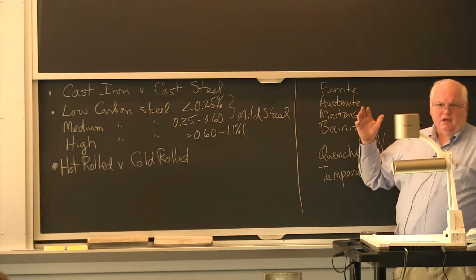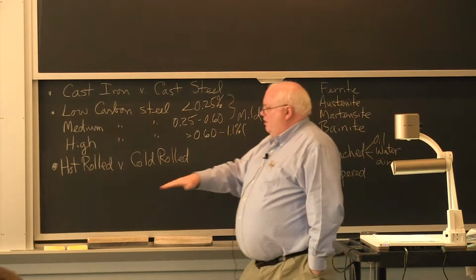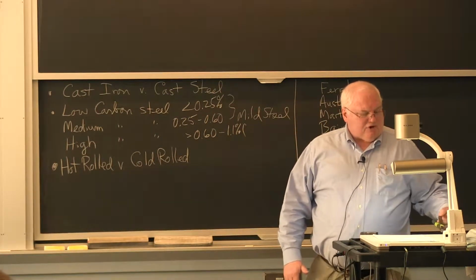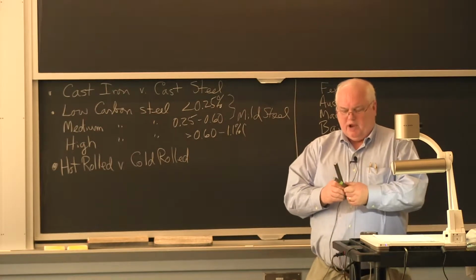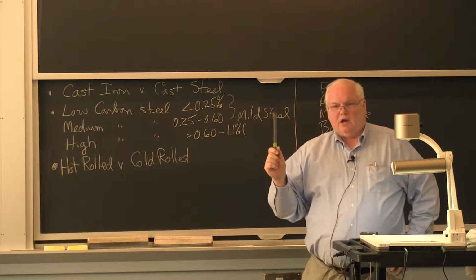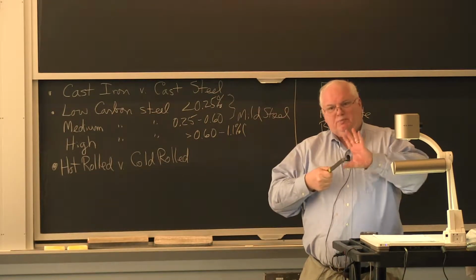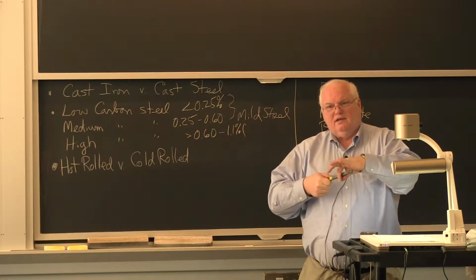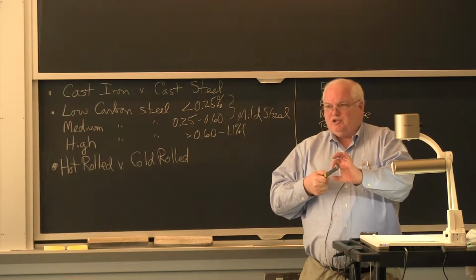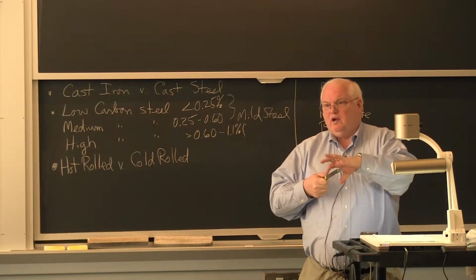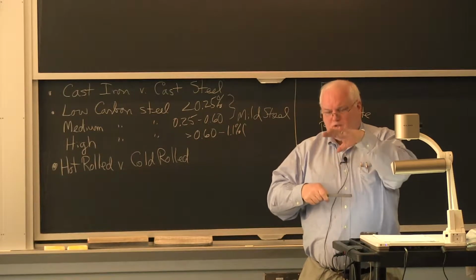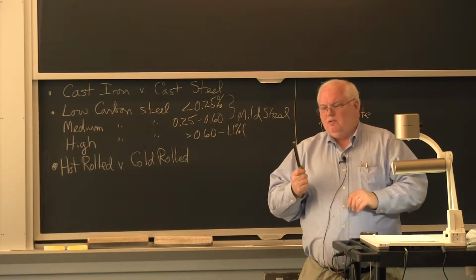Anybody have any question on that terminology? So when you say hot rolled and cold rolled, if you're talking bar stock, I can have 1/2 inch bar stock, like this stuff. It's got a magnet in between. That could be cold rolled because the mill to squeeze that could do it cold, even though it's 1/2 inch. It might have started out as bar stock of 1 inch or 1.5 inch, round or square. And a mill can have enough separating force to squeeze this cold down to this.